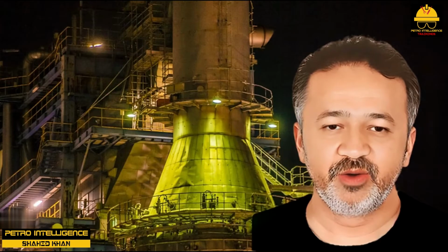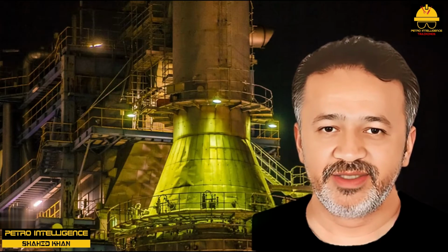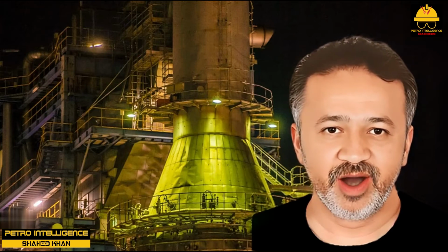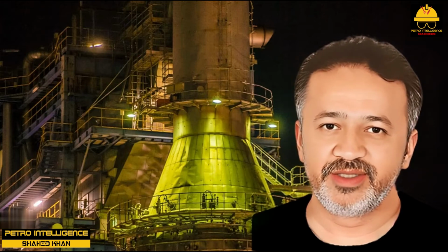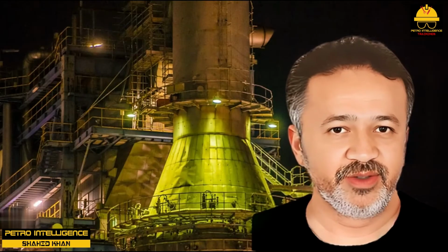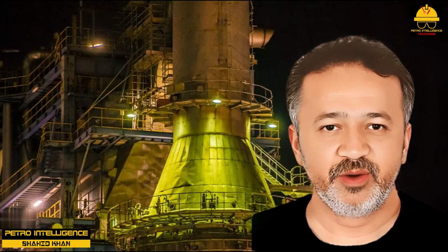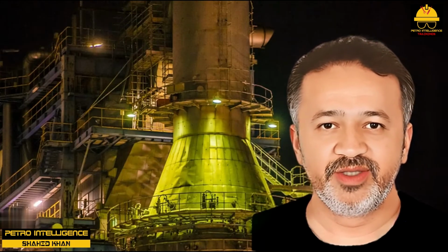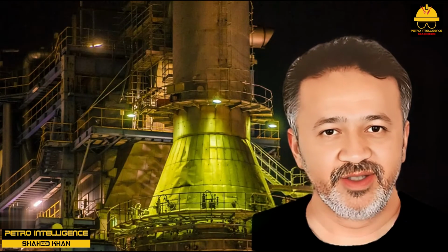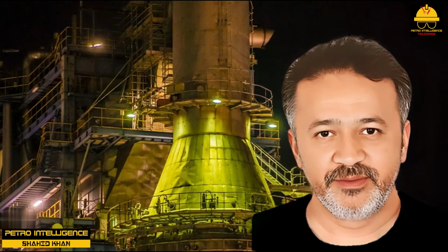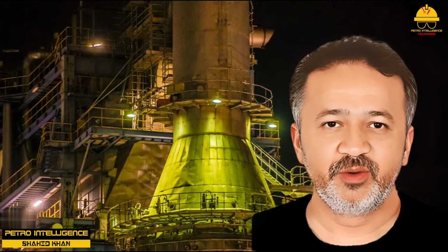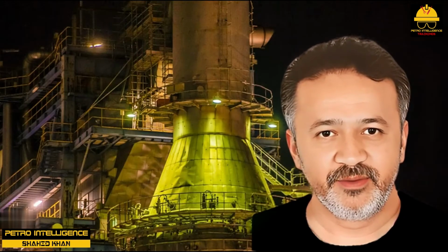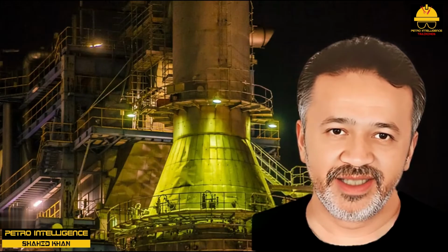Secondary combustion, or afterburn. In the preceding paragraphs we discussed how operation without enough combustion air, on the wrong side of the point of absolute combustion, leads to inefficient combustion of fuel. Apart from the fuel wastage, there is another important and frequently occurring problem associated with this bad mode of operation. The products of incomplete combustion of the fuel, and in more severe cases even the unburned fuel itself, flow with the flue gas up through the convective section and up the stack.